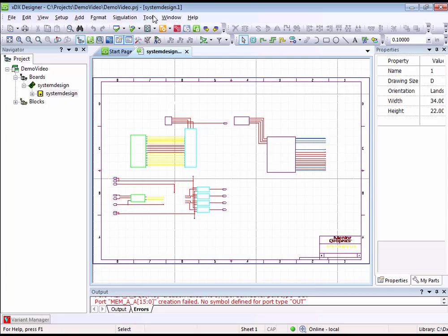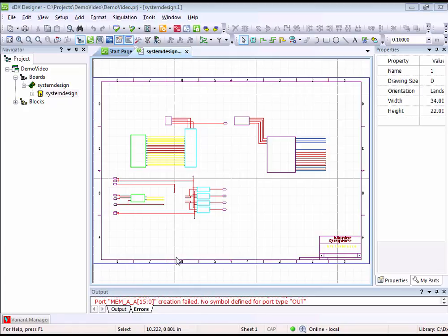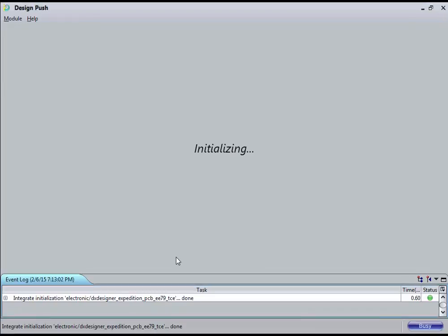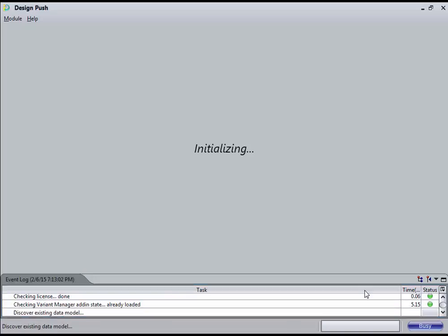In this sequence, we will first release the design and afterwards generate a new revision to make changes to the design. All those steps will be handled via the integration. Therefore, we assume that our design is finished and we can release it. We use the release function in our integration. It is implemented in the Save module. In our example, our design document in Teamcenter will be automatically released with this function. Alternatively, it could also trigger a release process within Teamcenter.